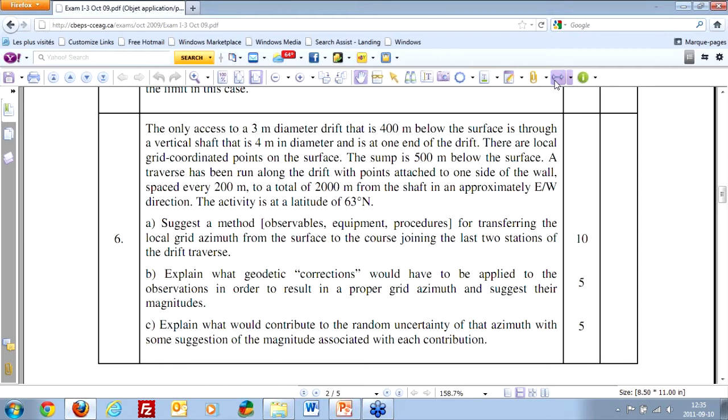And so, if we then talk about putting plumb lines down, we have to figure out what sort of weight would go on, because we use the value for the weight later on when we're doing some of the uncertainty calculations. And usually the general rule is that you use a weight that is 1/3 of the length, where the length is in meters and the weight is then expressed in kilograms, so long as it doesn't exceed the breaking strength of the wire. If we take the 400 and divide by 3, we have 133 kilograms, which is still within use.